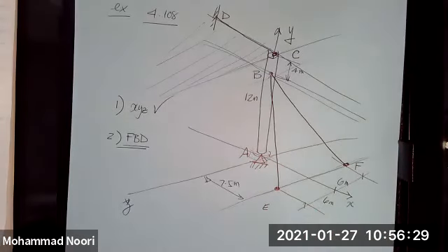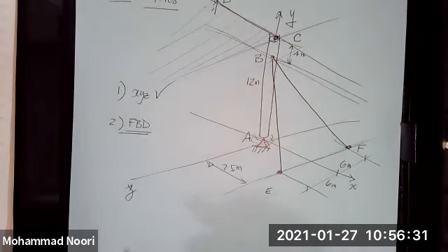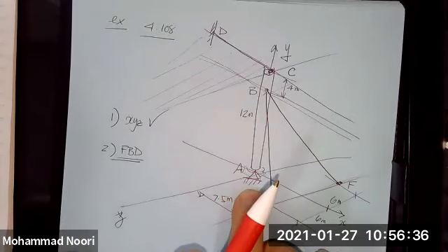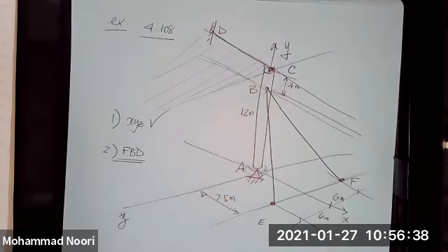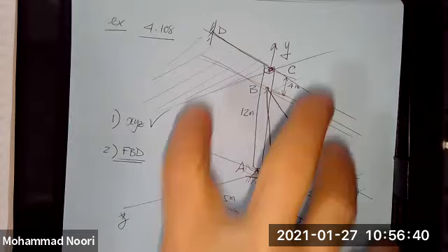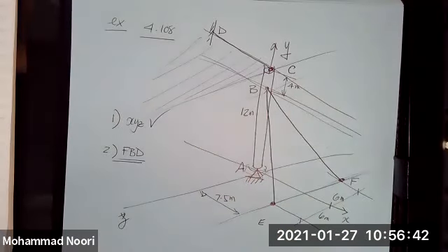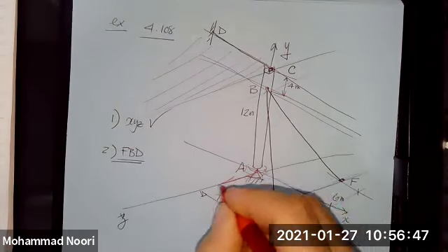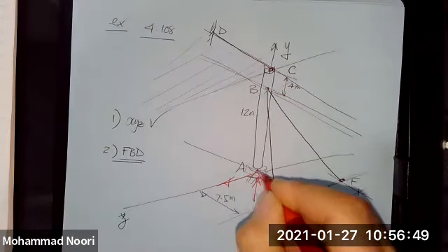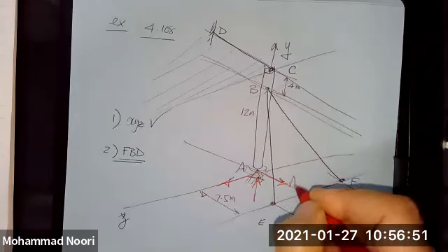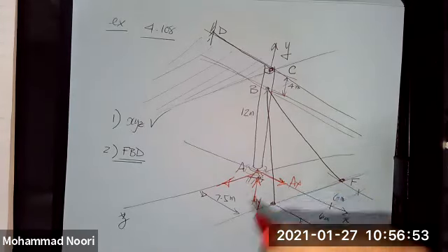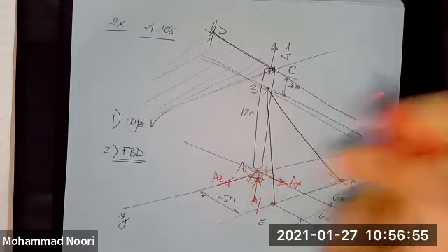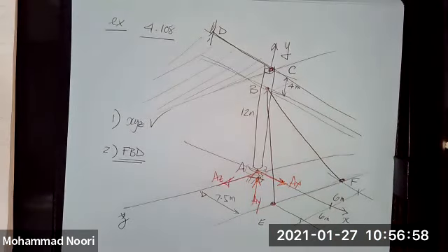So to save time, I'm going to show the unknown forces on this diagram using just a different color. So A represents 3 unknowns, and typically, like in 2D, I would assume an arbitrary direction for these unknowns, that if I find later on by solving for them, they came out to be negative, that means my assumed directions are wrong.